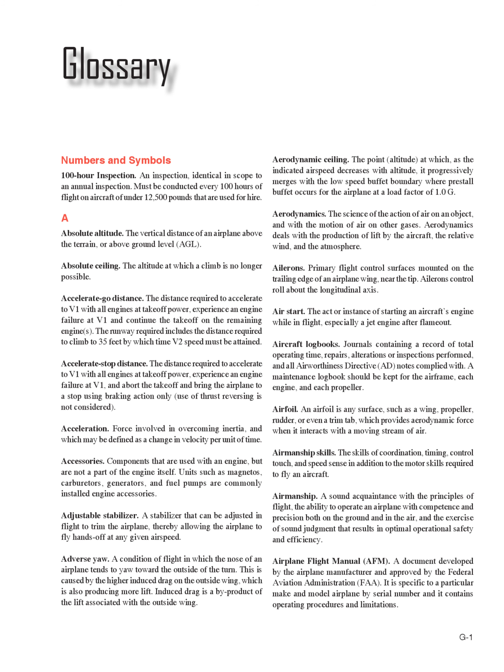Accelerate stop distance. The distance required to accelerate to V1 with all engines at takeoff power, experience an engine failure at V1, and abort the takeoff and bring the airplane to a stop using braking action only. Use of thrust reversing is not considered.